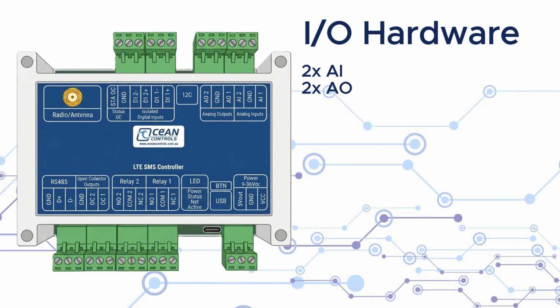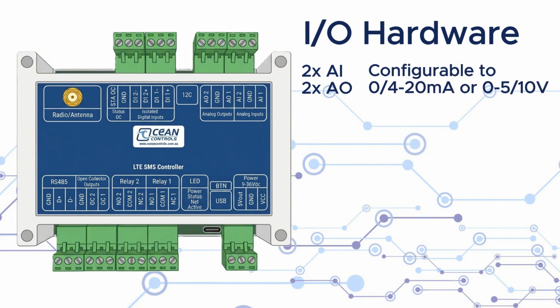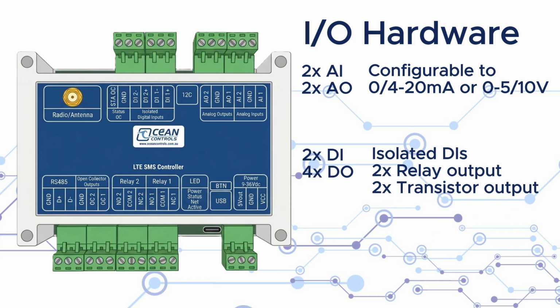Both are programmable to accept 0 to 20 milliamps or 4 to 20 milliamps, and 0 to 5 volt or 0 to 10 volt signals. 2 digital inputs and 4 digital outputs, the digital outputs consisting of 2 relay and 2 open collectors.